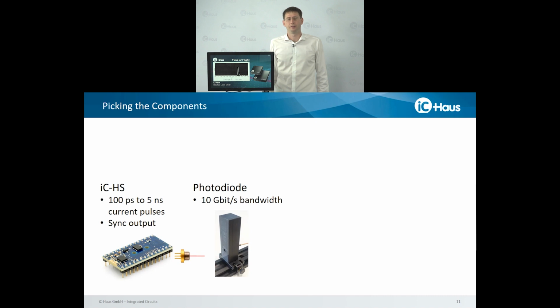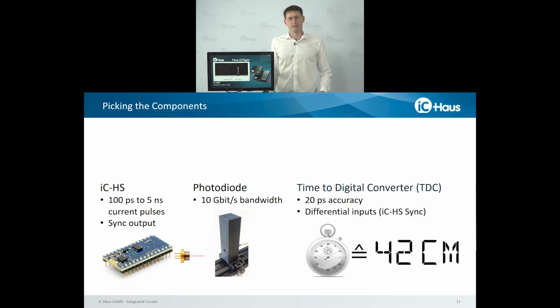And from that on, we can more easily go about the post-processing. Next is our time-to-digital converter, TDC. In our experimental setup here, we have ranges from a few centimeters to about 1 meter in distance. If we want about 1 centimeter of accuracy, we can use this to check out what the accuracy of the time-to-digital converter needs to be.